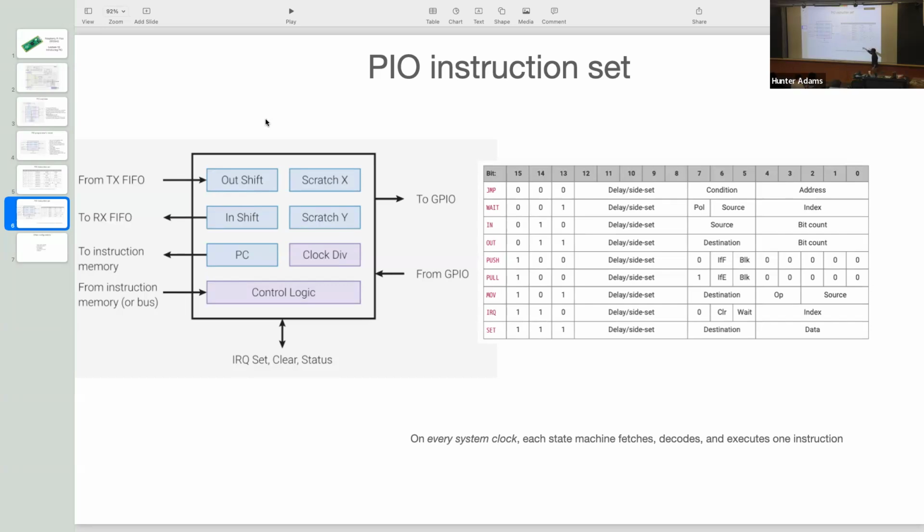And so that means with this set instruction, you can only set these registers to values that are as large as 31, but no higher. In the event that you wanted to initialize one of these register values to a number bigger than that, you'd have to come up with some other mechanism of getting that number into that register.